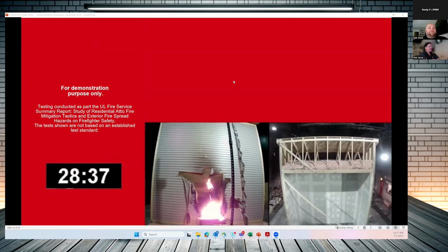And I think we cut off the camera at around 30. And you can just see how nice that material still looks. The soot is just from the incomplete combustion of the fuel they're using, but the stone wool itself is completely unharmed. So when it comes to fire protection, having a non-combustible material within that design really plays a pretty pivotal role in keeping these buildings safe and durable.